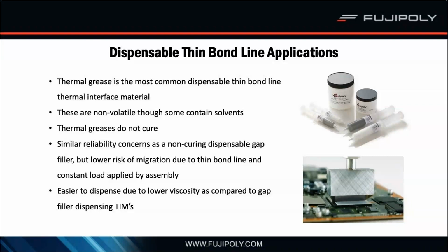These options are really going to change depending on the manufacturing requirements, if you're dealing with a high volume application versus something that's just building a few hundred units. Some customers have even taken advantage of the low viscosity of the material, and they use a silk screening or screen printing process just to get those thin bond lines and consistency out of the grease.